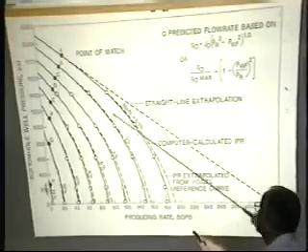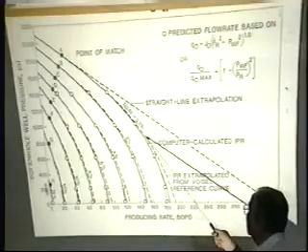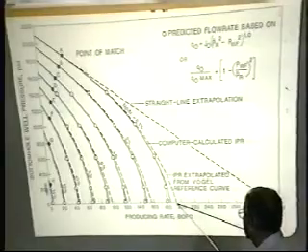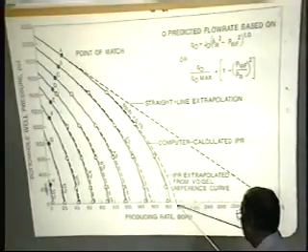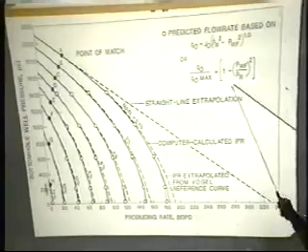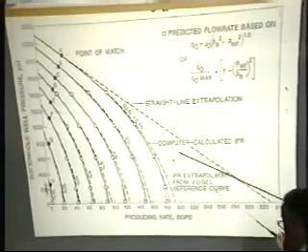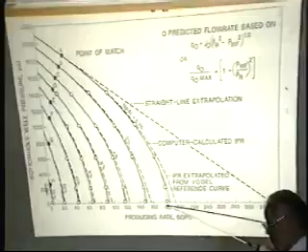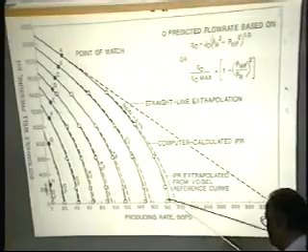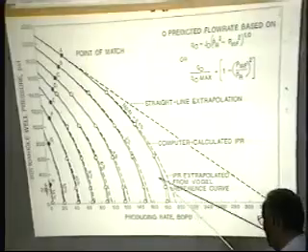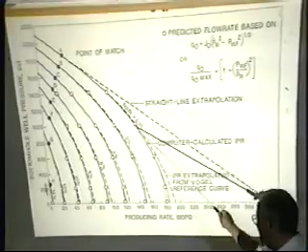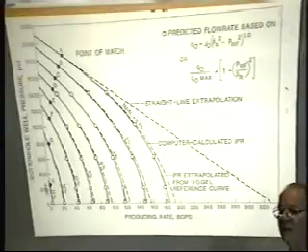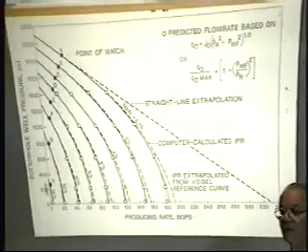If you take his inflow performance equation, which is the dotted line here, it says the absolute open flow potential of that well is about 195 barrels of oil per day. Now, if you take this form of equation and use it, you'd get the circles, and that shows that you would get slightly less. For practical purposes, there isn't much difference in the answer here, but conceptually it says that the delta P squared form equation fits his reservoir simulation model better than his empirically backed out inflow performance equation.